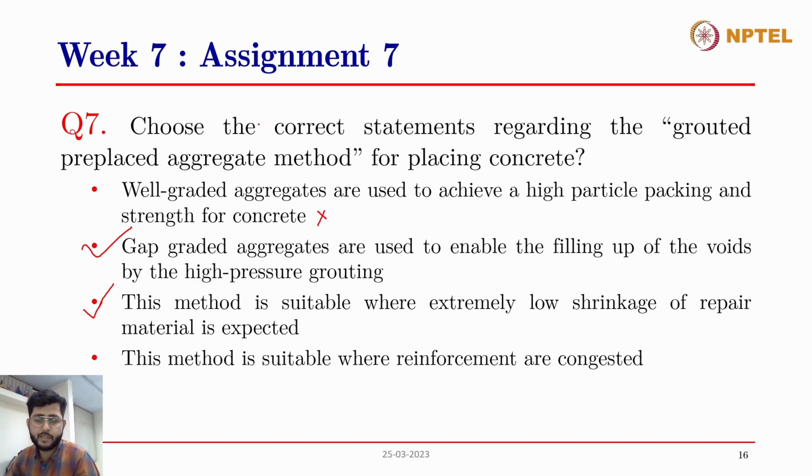Let's discuss all the statements one by one. The first statement is well-graded aggregates are used to achieve a high particle packing. Well-graded aggregates will give you a high particle packing, but the problem with this method is that we have to pump the grout into the structural element through a very small sized hole.